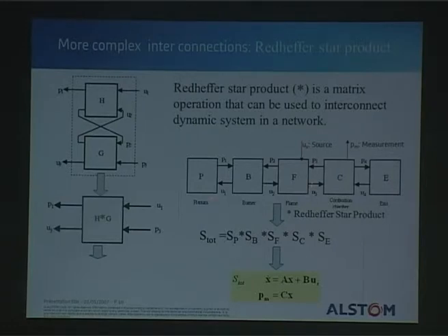We have these measured flame transfer matrices. We fit state space equations to that, so we have that. And for the burner, we have partly some analytical expressions, and we have analytical expressions for the exit condition. And then we use a method that's standard in control theory, the Redheffer star product, with which you can very conveniently combine all these different submodels into one big model that combines everything.